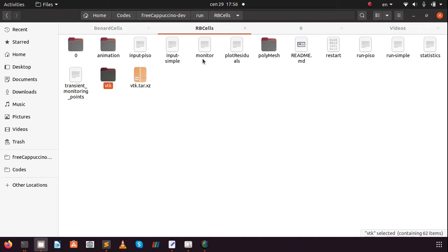non-stationary mode. So in OpenFOAM, when you say that you're using simple, it's only for stationary runs, as I understand. Correct me if I'm wrong. For non-stationary runs, they use PISO or PIMPLE algorithm. The thing that we have here is, I don't like the word pimple, so we have only PISO algorithm, but it has an option for under relaxation of pressure and velocity fields.